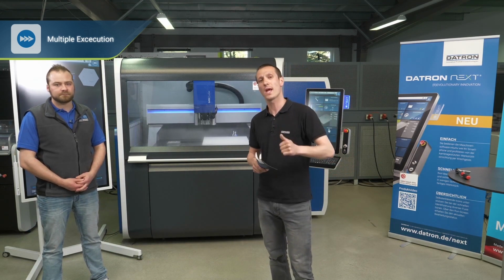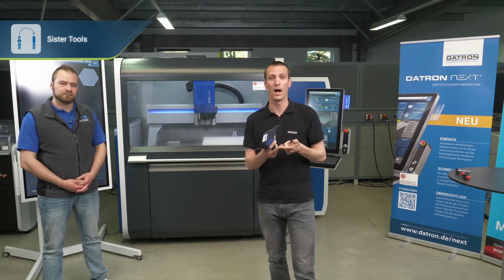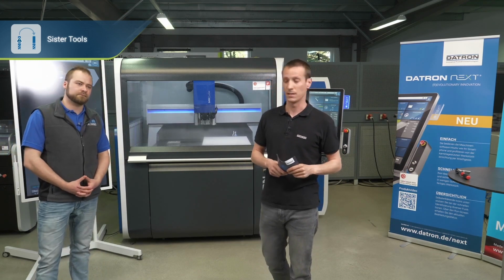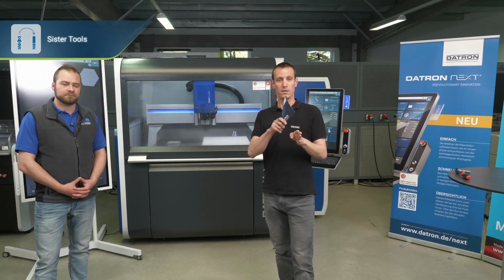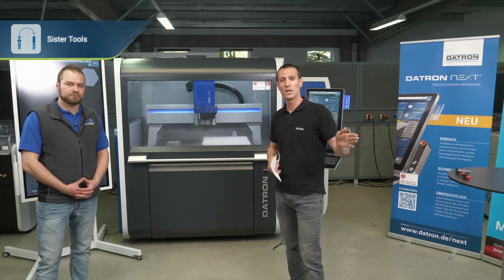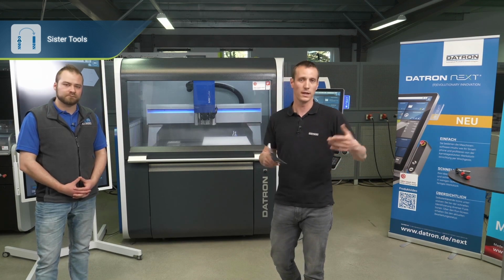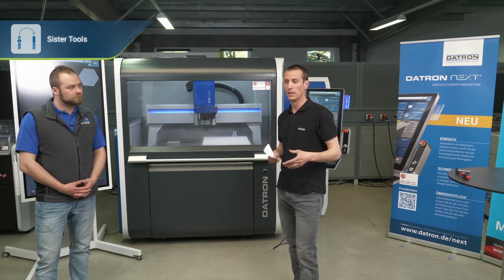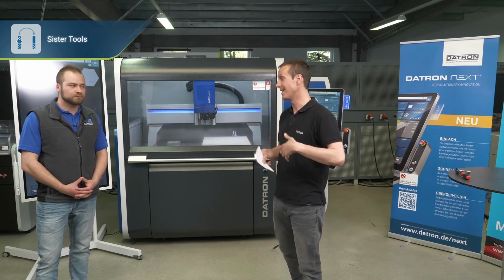It will check if there is a certain limit of a path where the tool has gone, or a time has expired, or if there is a tool breakage detected by the tool probe in the back of the machine. So in fact, you can set up the same or similar tools, the same tool type, multiple times in your tool magazine and just keep the machine running, and whenever it detects offsets in the length, or the different times, it will automatically change and continue the program. You don't have to worry about changing the tool manually and interrupting the program.